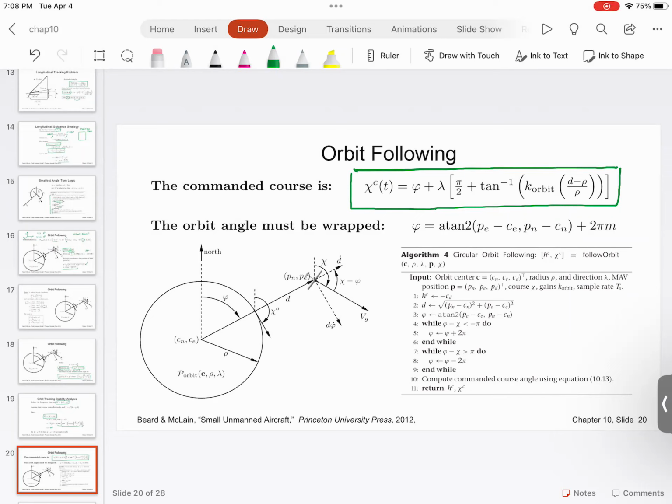Is the orbit also available manually, depending on the size of the plane and stuff like that? Yeah, so basically that depends upon the airframe size. So we don't have to use the signal control method for tuning and stuff like that. We are not looking at PID. PID, at the end of the day, is a linear technique. Lyapunov technique is a nonlinear technique. PID gives you the local control. Lyapunov technique gives you the global control. Something to keep in mind.